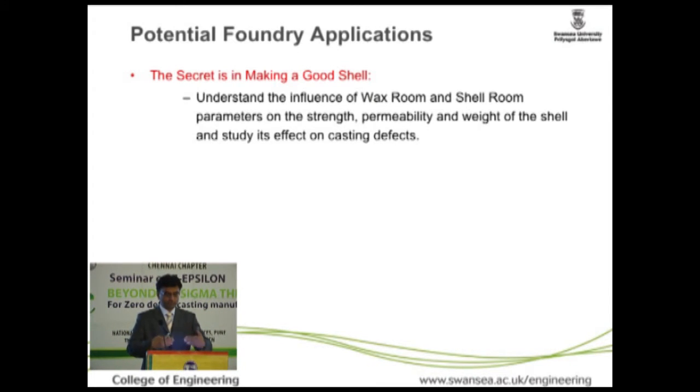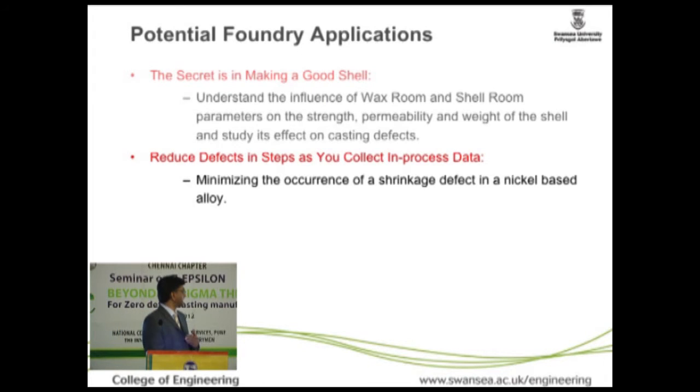The first step, we start with whatever you've got. This particular example, which we are discussing with shrinkage data and nickel-based alloy, you might have data on only, say, 20, 30, 40 heats. Then you get a sort of difference in rejection rate. And then you can see that rejection across the components, because you use the same furnace for 5 or 6 different families of components. So you can see the variation across components, maybe pick up some components which are sensitive, and then you look at their methoding design.